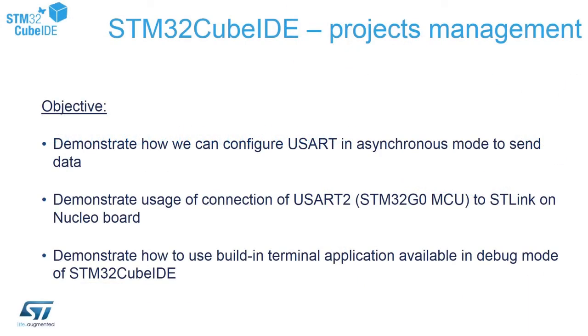So the objectives of this part are the following. I will demonstrate how to configure the USART tool in asynchronous mode to send the data, and then how we can reuse the existing connection between the USART of our microcontroller on the Nucleo board and the ST-Link, and then use the virtual COM port on PC to communicate with the micro. And then we will reuse the existing built-in terminal application, which is a part of STM32Cube IDE.